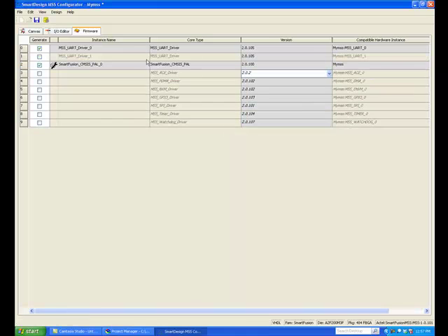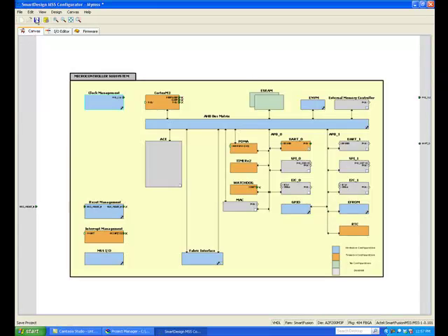Next, right-click the M2F Reset N pin of the Reset Management block and select Clear Attribute. Then right-click again and select Promote to Top Level. Click the wrench icon on the fabric interface block.